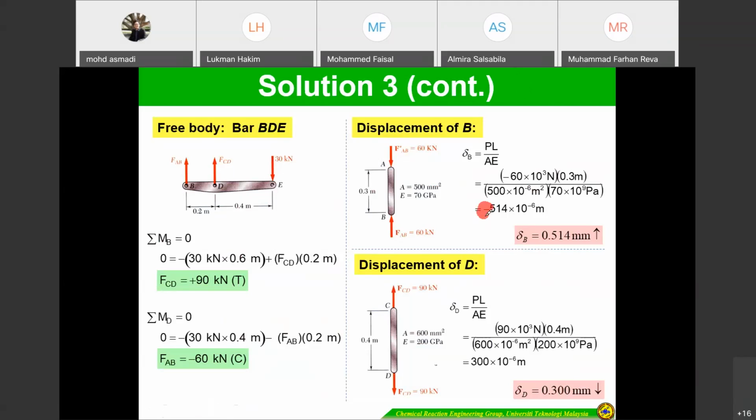if you want to present your result, you replace it with the arrow, so the negative disappears. If you look here, the arrow is pointing up, right? So that means this bar is compressed. That's why we remove the negative to represent compression, or you can write it as compression, and then you can remove the negative.